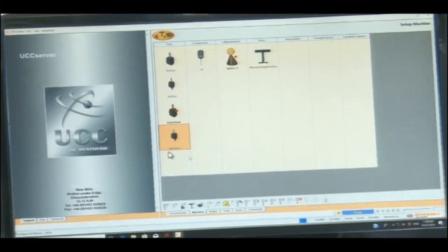There are certain purposes that this UCC controller accomplishes: data transfer and control, communication with the controller, and specialized controller features like CMM measuring accuracy enhancement, different measurement coordinate systems, and digitizing and scanning abilities. Data filtering can also happen using this controller, because we can create the file in IGS format.